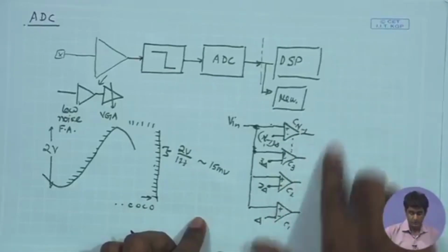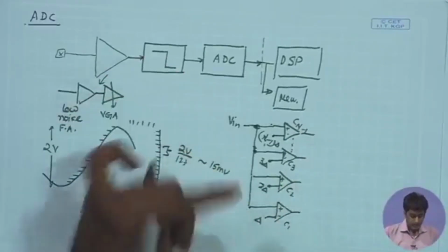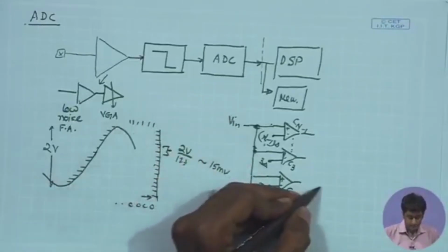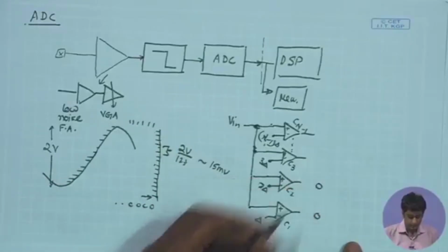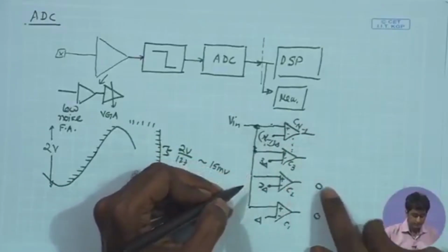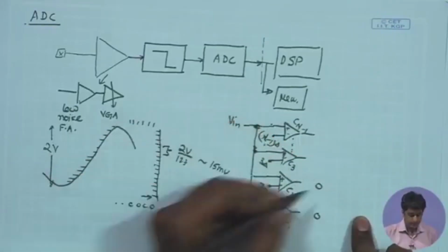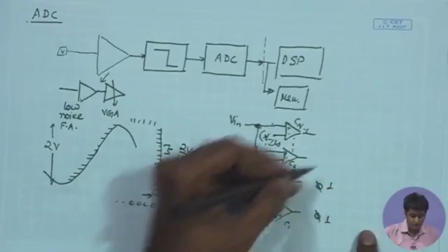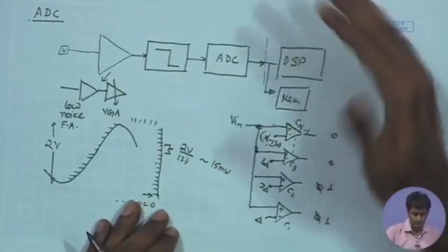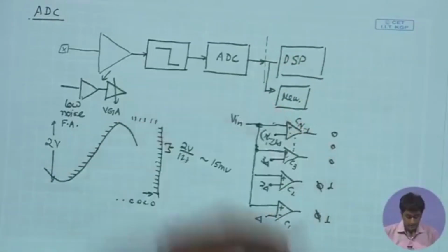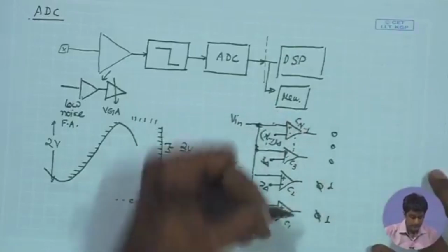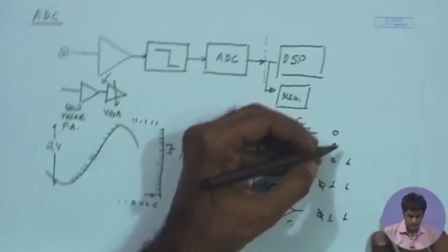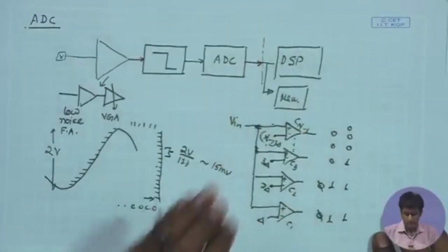So, we will get straight 0 outputs over here, and as the signal goes up, suppose it is higher than 2 delta, but lower than 3 delta, in that case we will have the first two comparators giving us 0 0, whereas since it is lower than 3 delta, I am sorry, I will be getting 1 and 1 at the output of the two comparators. If the signal is higher than 2 delta and other two comparators, all the other comparators will be giving us 0 0, and likewise suppose the signal is higher than even 3 delta, then I have 1 1 1, but if it is lower than 4 delta, so the fourth comparator onwards all the values will be 0.